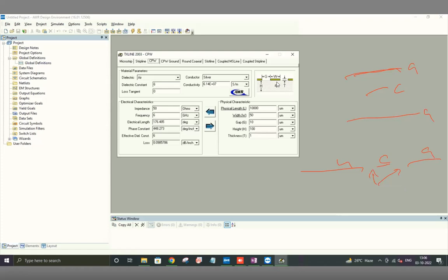So if you think about this, this is also one other way of transforming the coaxial line, where we have removed it from the 3rd dimension and put everything on the plane. So the advantage here is that all the terminals are now on the same plane. So from the point of view of interfacing this transmission line to other circuit elements, which could be some components or chips, which you are placing on the circuit board, it is easier because you have access to both the ground terminal and the center terminal. Whereas for the strip line, the center terminal is actually buried inside the ground plane. So it can be very tricky to access that. So this is called coplanar waveguide.